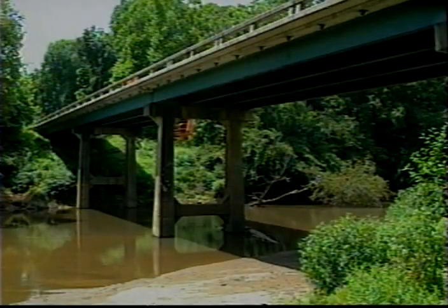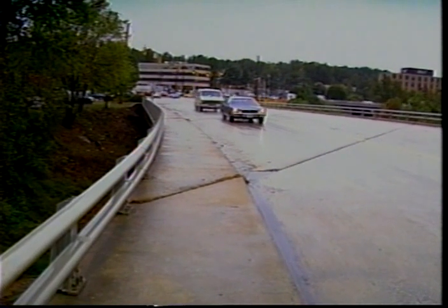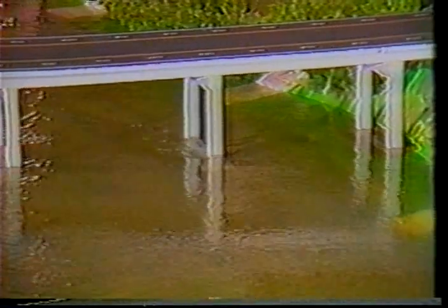The waterway appraisal evaluates how well the waterway opening allows water to flow through it. Evaluation of channel adequacy considers the probability of stormwater overtopping the bridge for the particular watershed where the bridge is located. Scour is erosion caused by the action of running water on streambed material around and beneath bridge foundations. The scour appraisal indicates whether bridge pier foundations or abutments are or may become unstable because of scour.